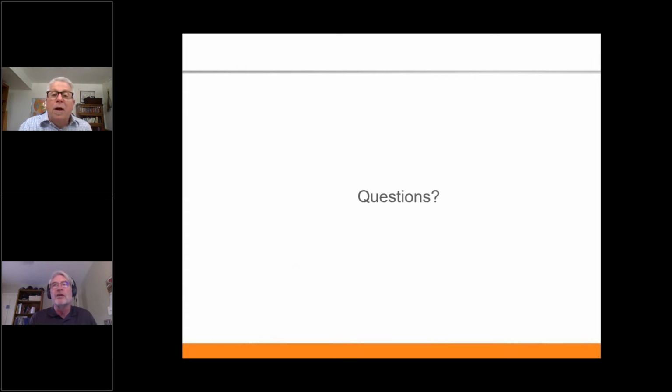And let's see, edge details on pedestal systems. Is there edge details anywhere for pedestal systems? Because they're very unique and different, many varieties. Yes, and I'm glad whoever brought this up, that's a great reminder. I should have brought this up when I talked about pedestals. Right now, you'll find that there's a minimum of pedestal systems that have a fascia or edge detail, or maybe a riser coming from a set of stairs, that first riser off of the deck. So you're going to have to look for the ones that have that type of assembly there.